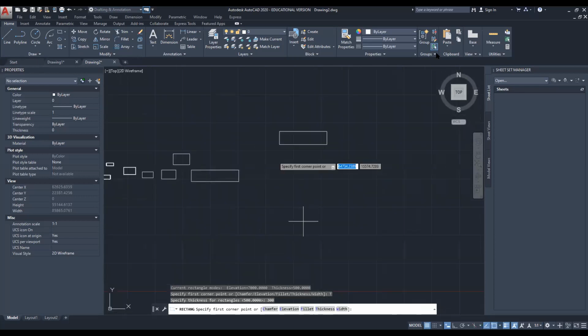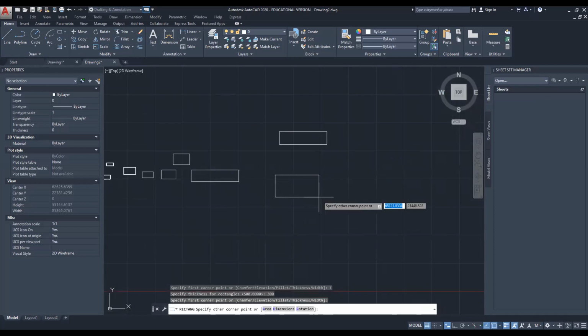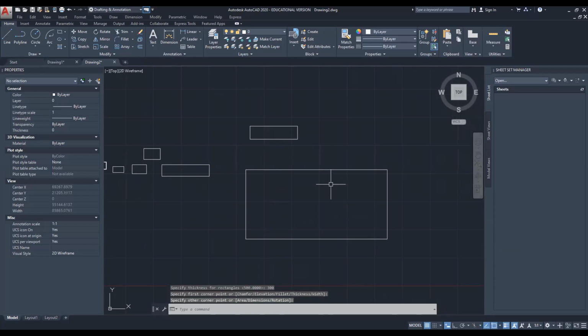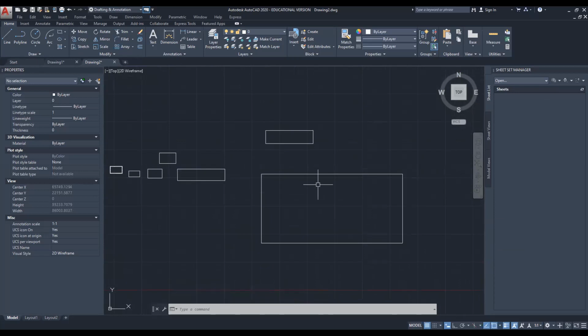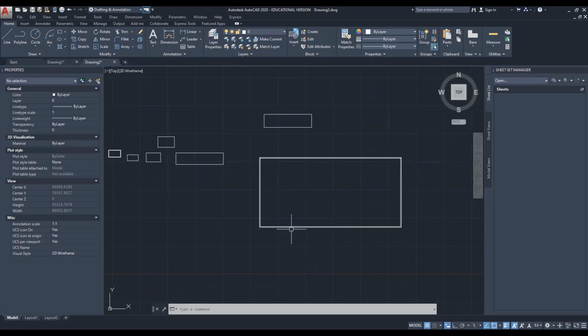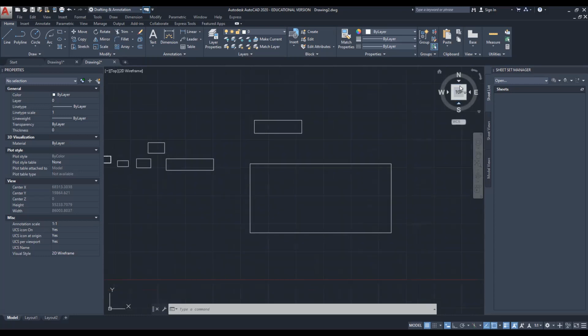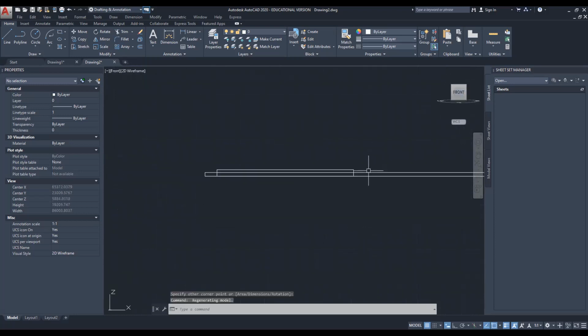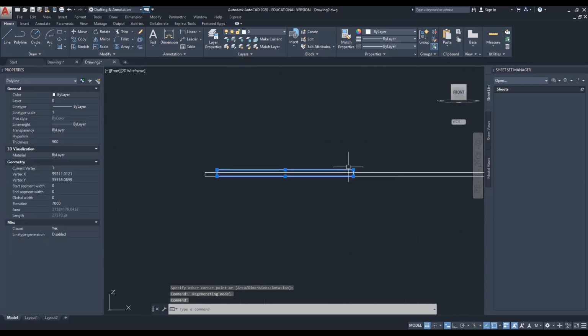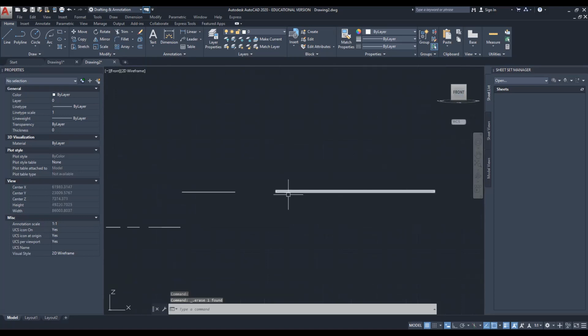After that, in the top view, I'm going to create a rectangle. This is the rectangle, that bigger rectangle. I have said that we are going to give thickness to the edges of this rectangle. So for knowing the thickness of this edge, we need to go to the front view. Moving to the front view using the view cube, you can see the rectangle we created previously; deleting that. So this is the rectangle we have created now, and it has a thickness of 300 units when compared to the 0 thickness rectangle.